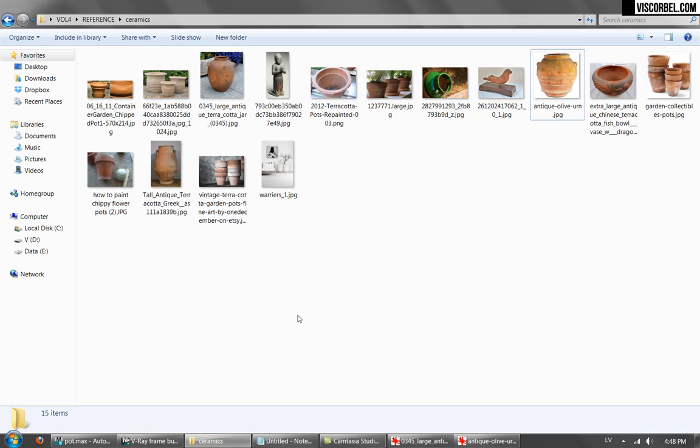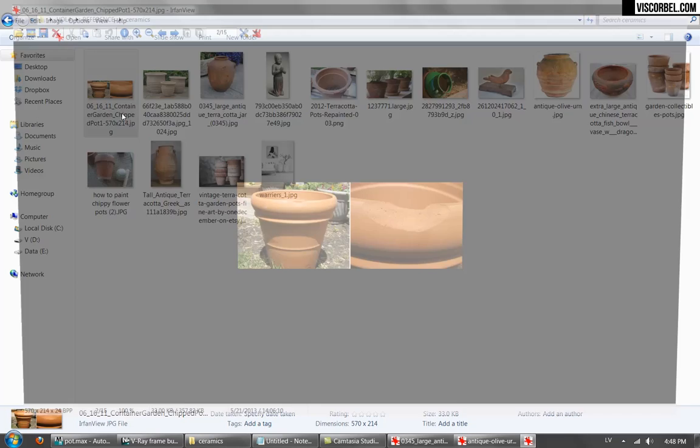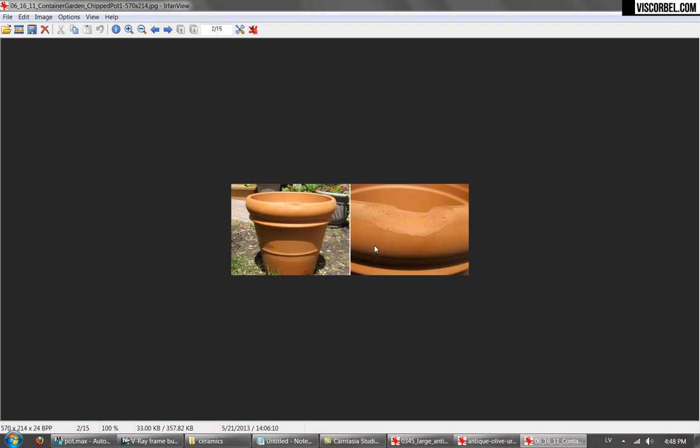Alright, so if we want to add some chipped edges, I want to do that with displacement. And if you look at this reference photo, you can see that the basic surface looks different than the one in these chipped areas. So I think we should probably split that into another layer as well.